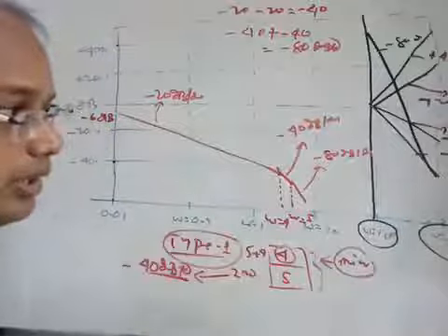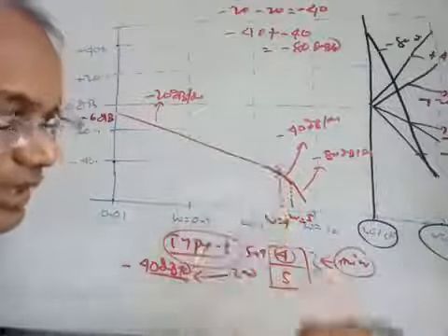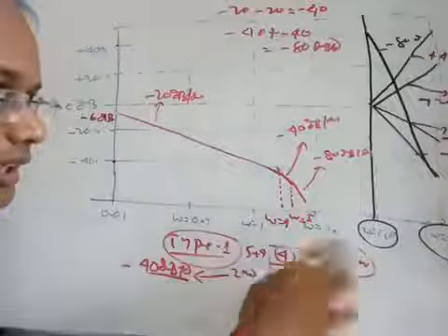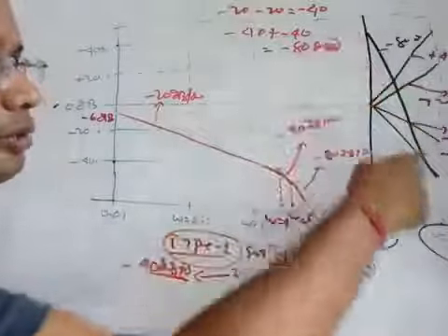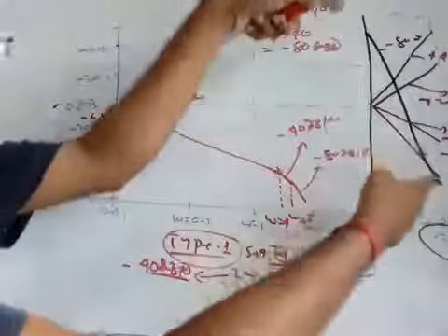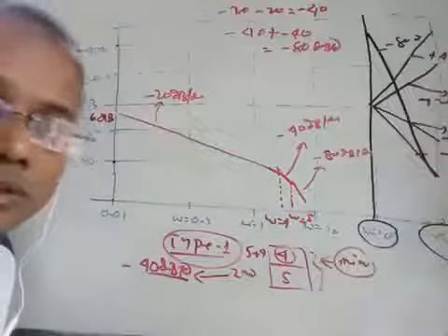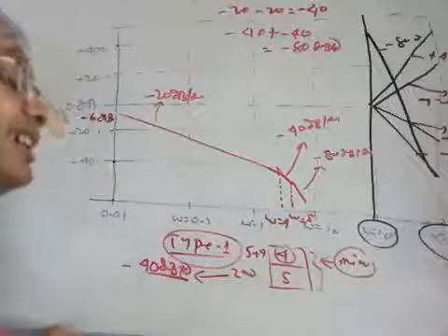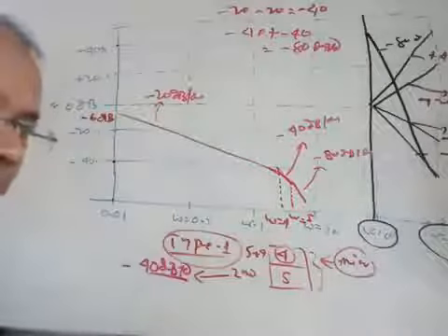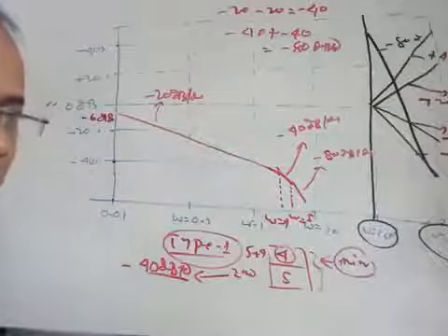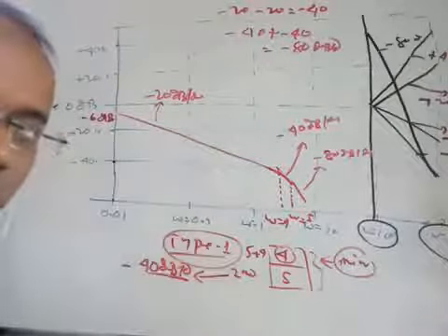And once you get the minus 80 dB per decade slope, this slope starts from omega equal to 5 and ends anywhere. You can draw this line. So to get this minus 80 dB slope, you have to join plus 40 to minus 40. That means the total magnitude change is 80 dB, and this is in the downward direction, so that is a minus 80 dB per decade slope. So that is the way you can draw for any type, any order, any factor, right? So this is how you can draw the Bode magnitude plot, right?